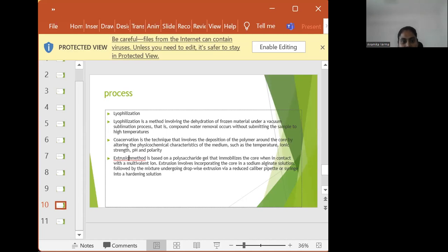With agitation, the core coating material is dispersed in the liquid manufacturing vehicle phase to obtain the appropriate size microcapsule. Agitation of the system is continued until the solvent partitions into the aqueous phase and is removed by evaporation. The process results in hardened microcapsules. Several techniques can be used to achieve the dispersion of the oil phase in the continuous phase. The most common method uses a propeller style blade attached to a variable speed motor.